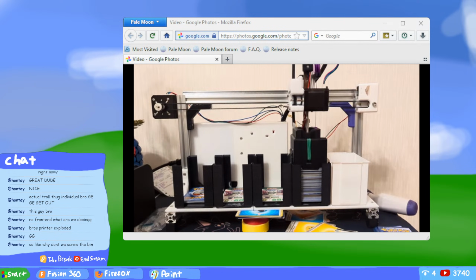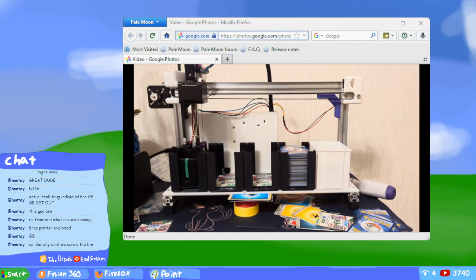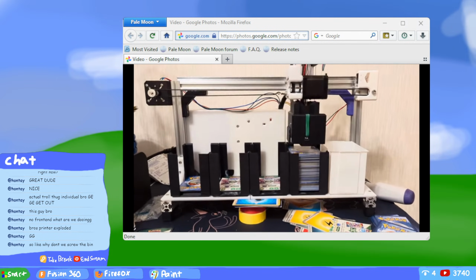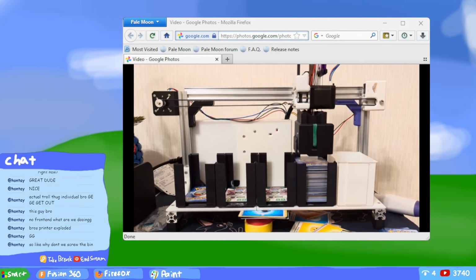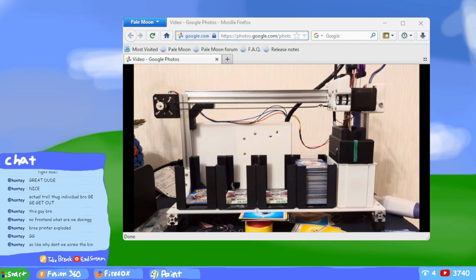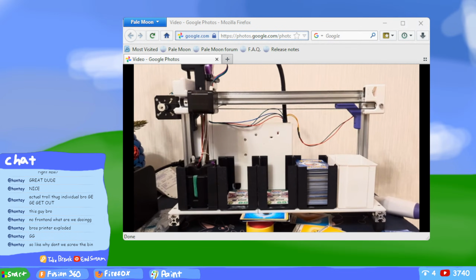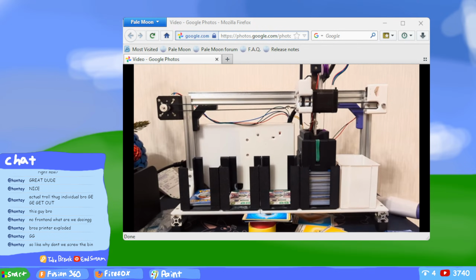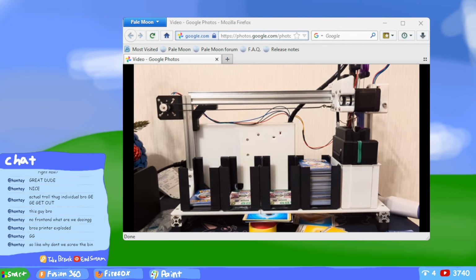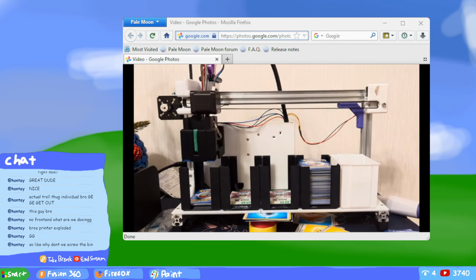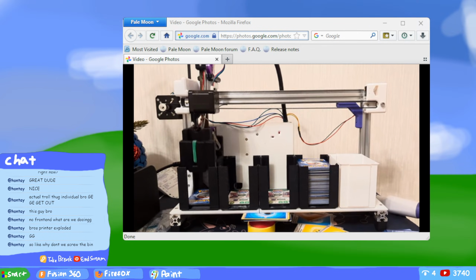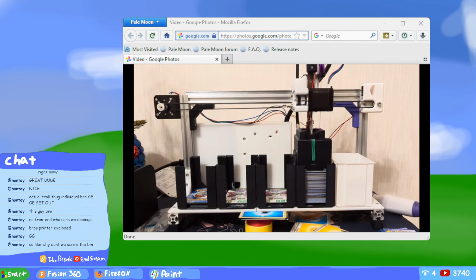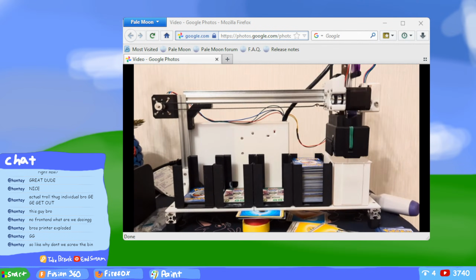If you screw the bin in, then it can't wobble to get perfectly aligned with the grabber mechanism. It's built-in tolerancing, basically. It's very convenient. You can see the bin that is full of cards. If you look really, no, I guess you can't really see it. Never mind. It's hard to see, but the bin is not screwed in because it needs to wobble a little bit so that it is centered around the grabber and the cards can be, you know, picked up.